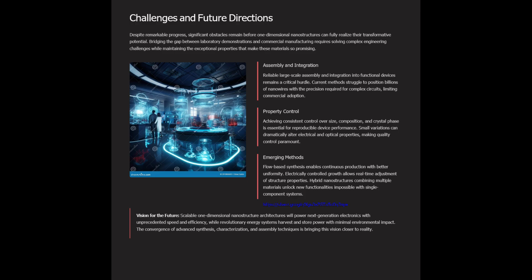Assembly and integration. Reliable large scale assembly and integration into functional devices remains a critical hurdle, and current methods struggle to position billions of nanowires with the precision required for a complex circuit, limiting commercial adoption. Property control. Achieving consistent control over size, composition, and crystal phase is essential for reproducible device performance. Small variations can dramatically alter electrical and optical properties, making quality control paramount.